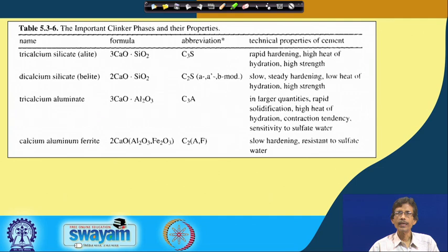So if you have a huge amount of sulphate in that water, it will react immediately with the C3A. So determination of sulphate in water is also important, because we know that as drinking water, sulphate is not good, and the health of your concrete, the building health, also depends on the presence of sulphate. So we should be very careful to know how much sulphate is there in the water used for making concrete.